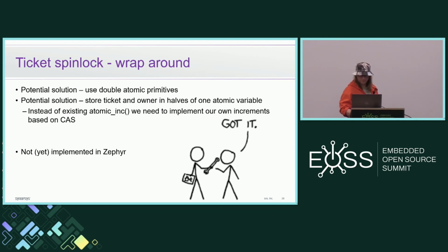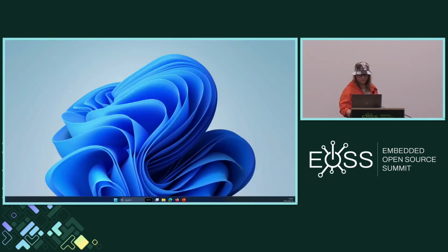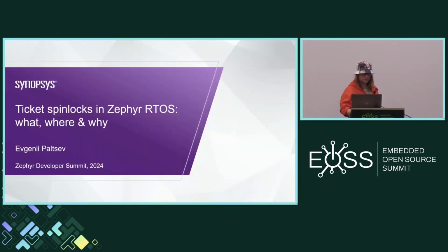Typically, the kind of things we are seeing here are implemented on top of cache coherency protocols. So if you don't have cache coherency, there is no such primitive at all. There can be exceptions, for example, Xtensa is a cache incoherent architecture. It actually does have an atomic primitive, it just goes through the cache. So different hardware is different. Yeah, possibly. I've seen these hacks for Xtensa, but I never actually investigated how it's done for them, just because luckily we don't have such a requirement.